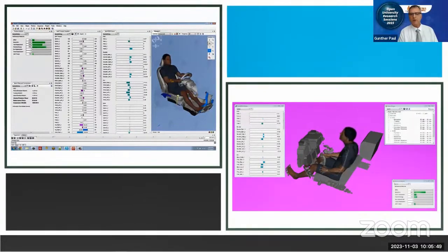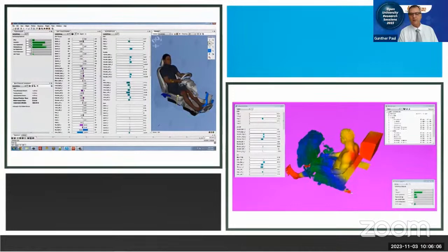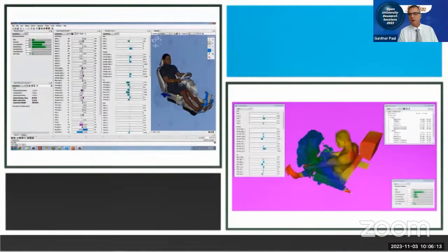In a jet, helicopter, or tank cockpit environment, thermal loading is often significant and can severely impede human operator performance. In this example, we see the digital human operator adjusting air conditioning controls before the thermal environment changes. Thermal zones are then shown and represent human thermal comfort perception, enabling redesign of ducts and outlets or system capacity to improve cooling performance.